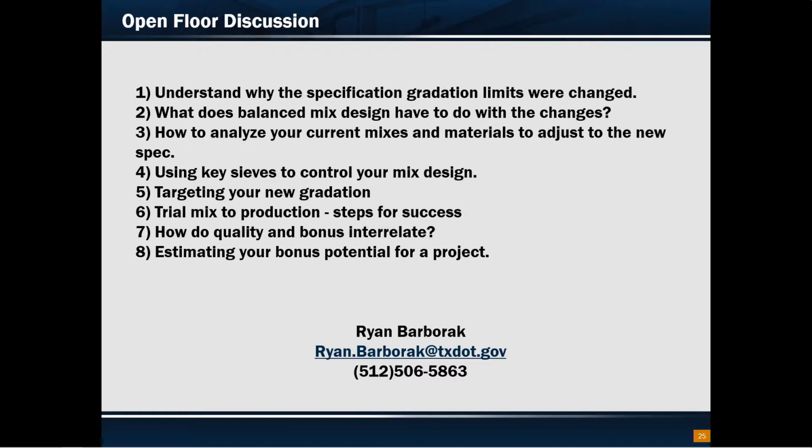And I was going to also answer number 2. I was going to turn it over to Jimmy, but what does this have to do with the balanced mix design? I know that question's come up, and we have had a lot of initiatives around the state. We're putting down test sections now to try to evaluate the balanced mix design. Where this comes into play is that one of the key factors we're looking at in terms of getting a balanced mix design is gradation. How can you adjust gradations to achieve a balanced mix design?